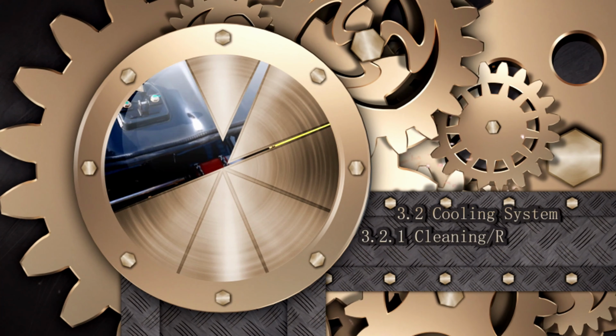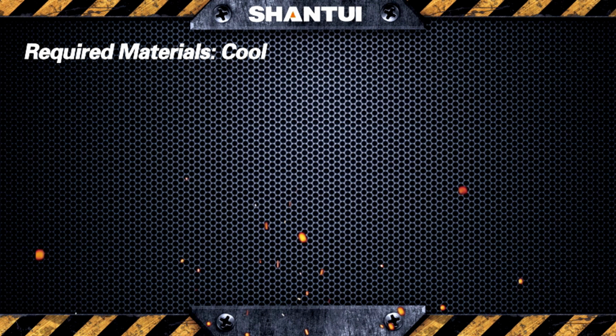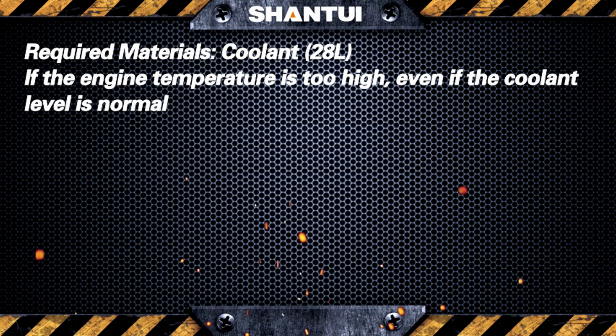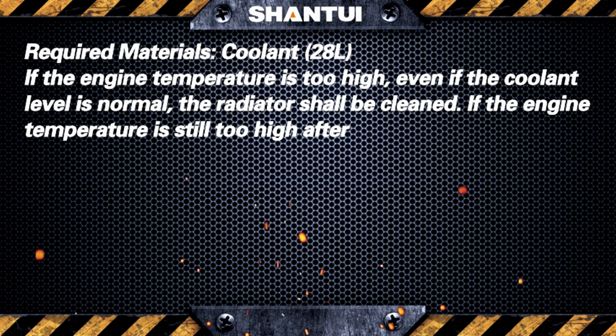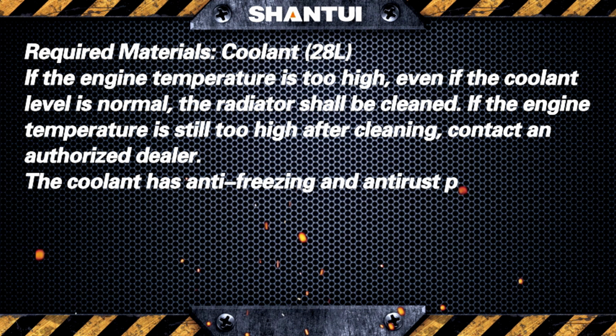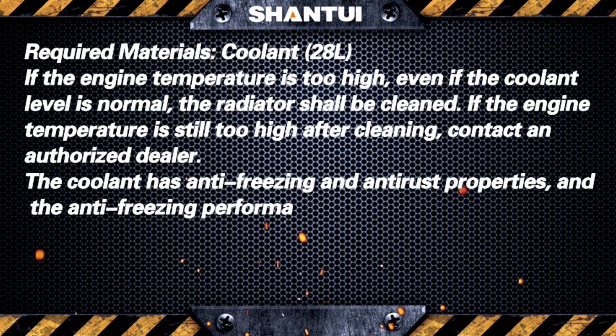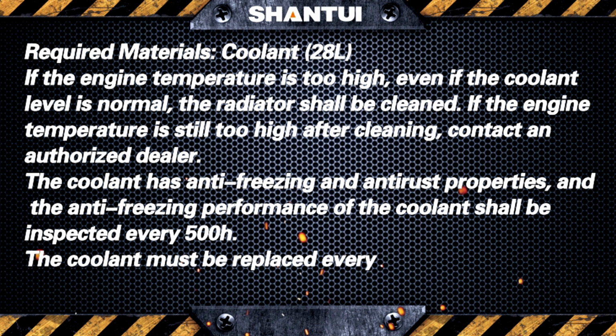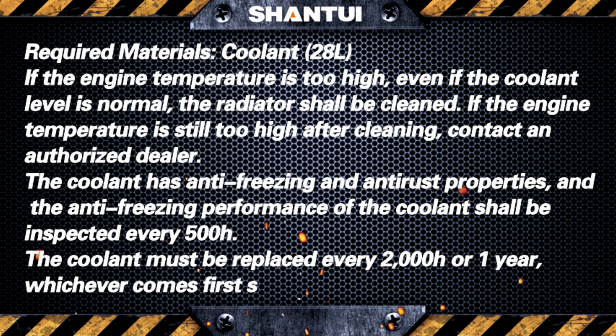Cooling system, cleaning/replacement of coolant. Required materials: coolant, 28L. 1. If the engine temperature is too high, even if the coolant level is normal, the radiator shall be cleaned. If the engine temperature is still too high after cleaning, contact an authorized dealer. 2. The coolant has anti-freezing and anti-rust properties, and the anti-freezing performance of the coolant shall be inspected every 500H. The coolant must be replaced every 2,000H or 1 year, whichever comes first.